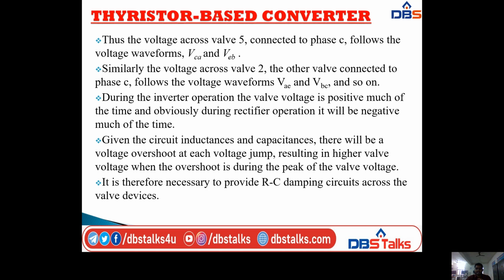Given the circuit inductances and capacitances, there will be a voltage overshoot at each voltage jump, resulting in higher valve voltage when the overshoot is during the peak of the valve voltage. It is therefore necessary to provide RC damping circuits, that is inductance, capacitance and resistance circuits, across the valve devices. Valve devices are nothing but thyristors.